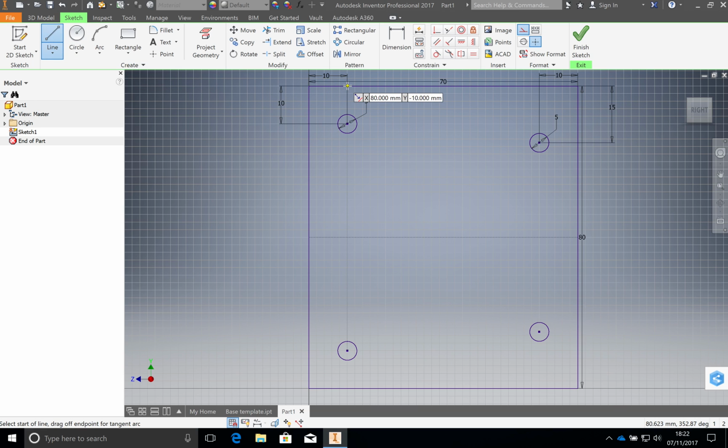I want you to come over by 20 millimeters, so that's 10, and then count another 5, and it's quite easy to see that that's 20. Start by clicking a line there. You want to come down by 20, we can see that extra thick line box there, and come across by 10. It should look roughly like this. So you've come down 10 squares and across 5, and because they're 2 millimeters each, you've come down by 20 and across by 10 millimeters.